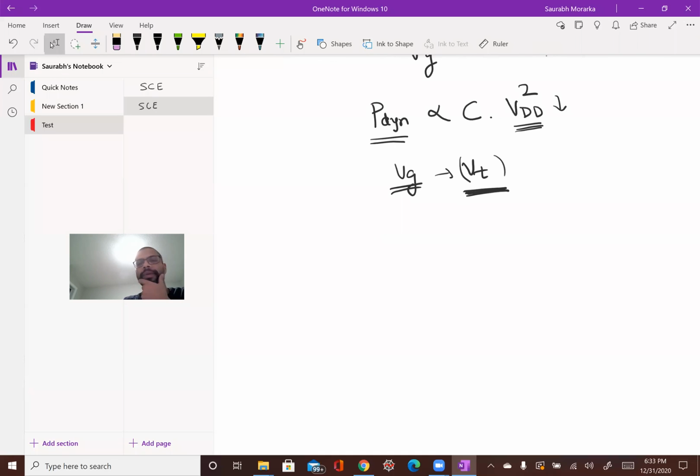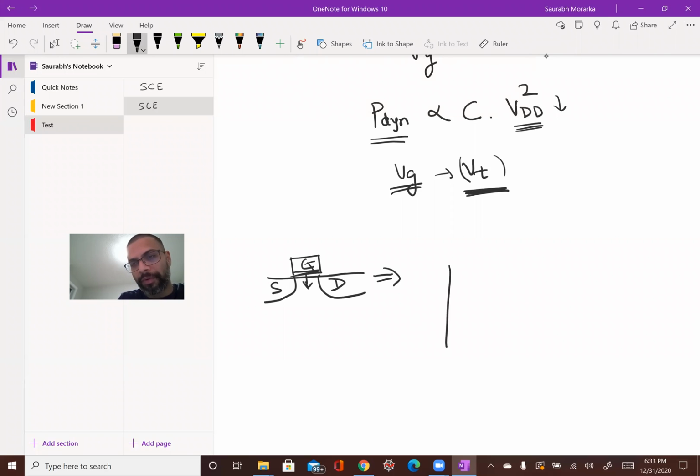Now one more thing to mention is, if we want to continue to improve the short channels, what are the device related tricks that people do, right? In terms of the architecture of the device, this is the main reason why people have gone from what used to be the planar devices, where there was a single gate that would control this region, which is the channel between the source and the drain. That has been slowly moving on to what became a FinFET device, right?